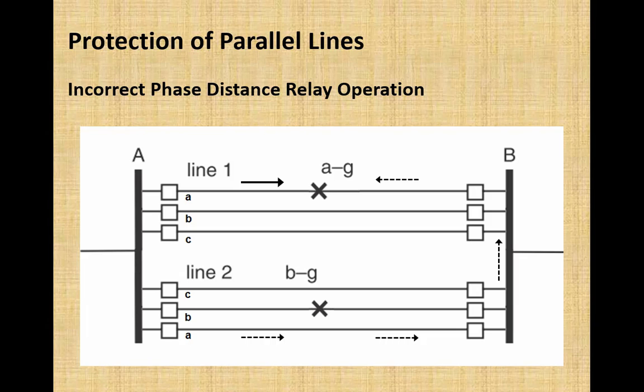In the presence of this fault, if a short circuit occurs in phase B of the parallel transmission line, that is known as a cross country fault. When lines are very close to each other, a flashover in one line may result in a flashover in a parallel line as well. That is a very common phenomenon in multi-circuit transmission lines.